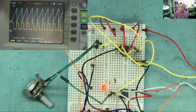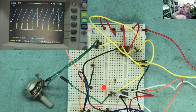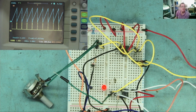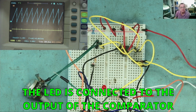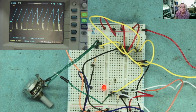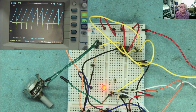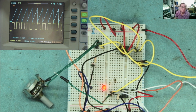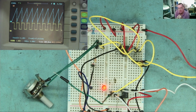So if I turn the reference voltage up, you see we can make the pulse width, that's the yellow trace that you see here, this yellow one. We can make that narrower, much lower duty cycle. And if you watch this LED, you'll see the LED is going off. Okay, it's dim. As I go the other way, the LED is getting brighter until we reach the maximum duty cycle there. Okay, that's about 50%, for example. So there's the pulse width modulator in operation using the 2 chips as I described on paper, and that works very well.